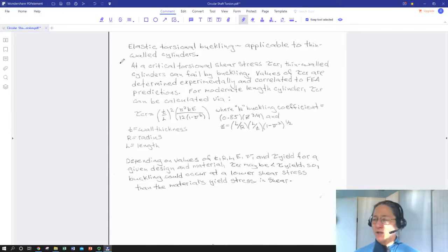Why would we be looking at a thin-wall cylinder in torsion? Because it's got a bigger moment of inertia for a given amount of volume in a cross-section area. So if you're lightweighting something, you're restricted to a certain material, so your shear modulus is fixed. You can get more torsional stiffness, quote unquote, bang for your buck by distributing that area out in a ring. And the larger, thinner the ring, the bigger the polar moment of inertia and the stiffer you get. What's the limit? Torsional buckling.